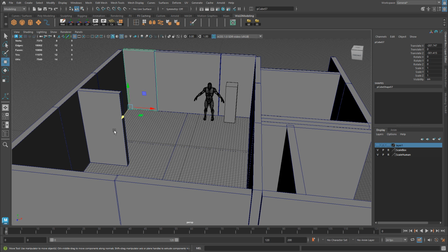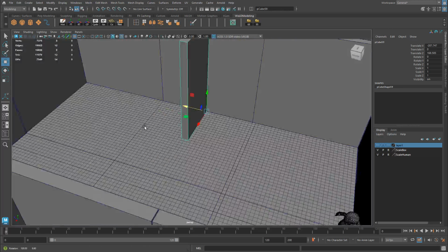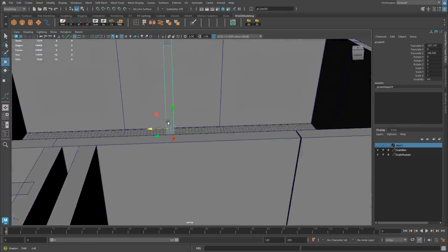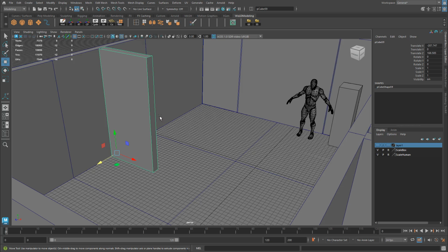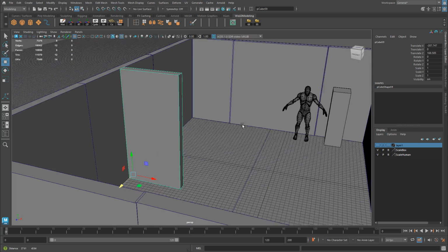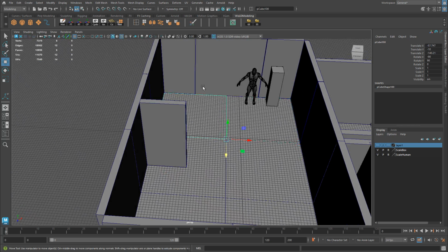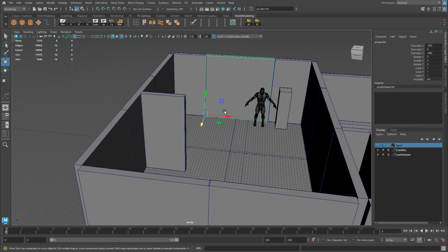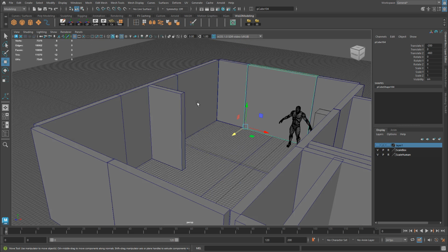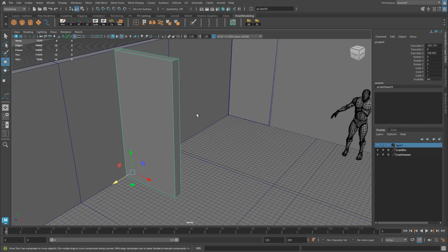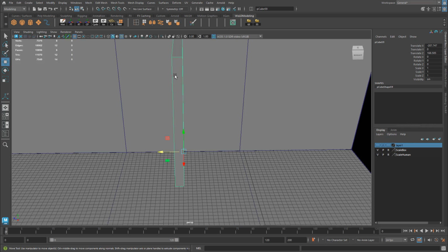And I made a small adjustment to the wall, to the 300 piece wall. I created a half size of 150 because I thought maybe some parts here I may want to, like for this one, I may want to have a window only in the center of the room instead of maybe 2 windows on each side. So I basically created a piece that's 150 by 300 in height. So 150 in width, 300 in height, and same depth.